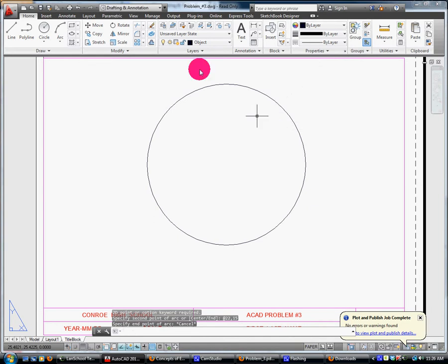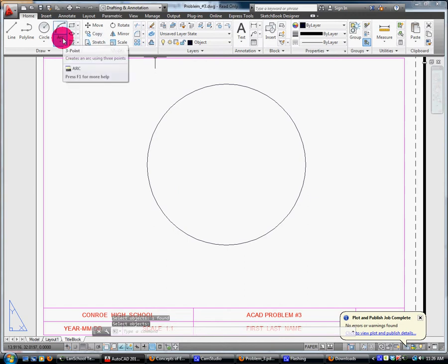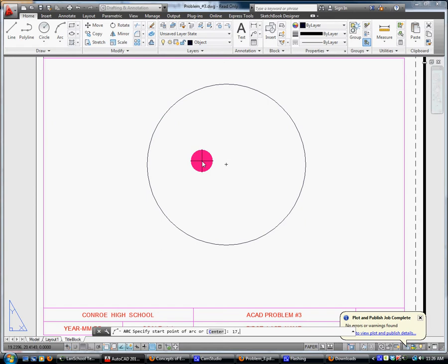I'm going to hit the escape key. I'm going to go back to my arc command. And this is going to sound silly, but on your keyboard, find the function 12. F12. Hit it. Once you have it turned off, copy the coordinates and it works just fine. Okay? So if you've got your dynamic input on, it's what's going to give you issues. So you have to hit F12, it turns it on, turns it off. So arc 17, 19, 19, 16, 22, 15, enter key. Okay?